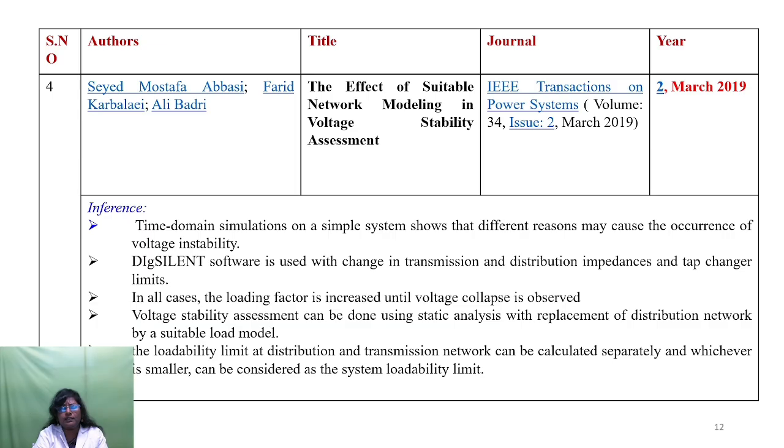So the voltage stability assessment can be done using static analysis, with the replacement of the distribution network by a suitable load model. But the loadability limit of the distribution and transmission can be calculated separately, and whichever is smaller can be considered as the system loadability limit.